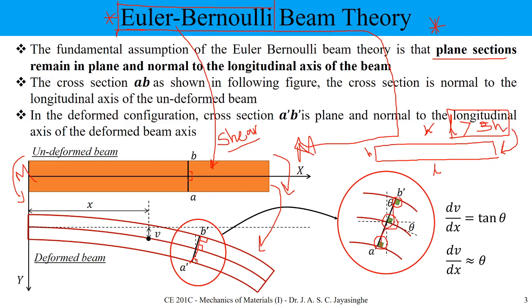But here we are working under pure bending, so simply this beam is going to bend mainly due to flexure effects. So we can neglect the shear component. If we neglect the shear component, we can assume plane sections remain plane after the deformation. Otherwise, actually we cannot assume or approximate like this. So I will clear this one first.